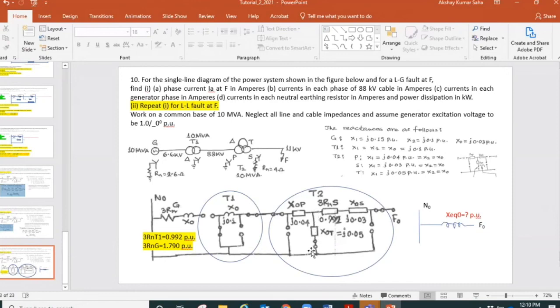Now I did follow this path already, so I come to this one. I continue pushing through the impedances. Can I go through this? No. So I leave it up to this point. Then I can continue this side. Yes, I can continue, this one because it's closed. So I arrive at this point. Then I cannot continue this way, so I drop that. Can I continue this way? Yes, there is some reactance I'm pushing, and then I'm coming to this path. Yes, I can continue. I reach the neutral bus. So this is now complete, and the last one is opening, so I cannot continue down.